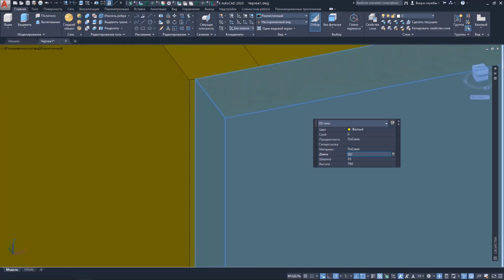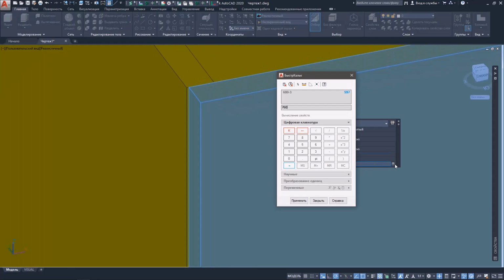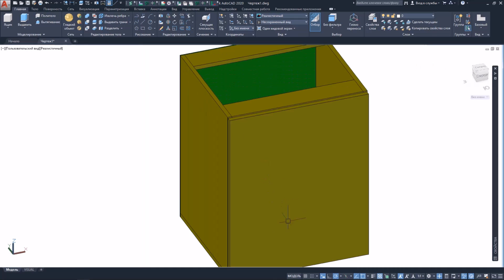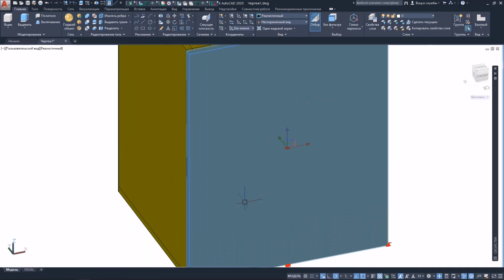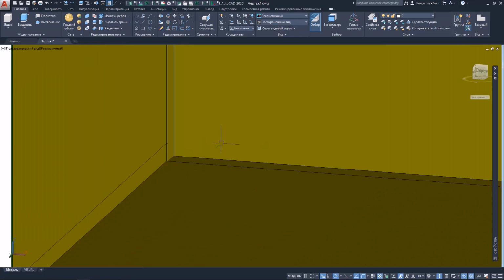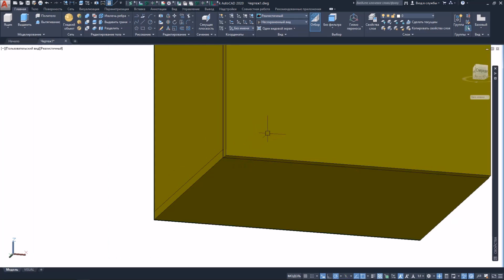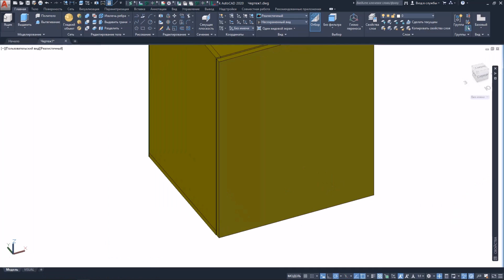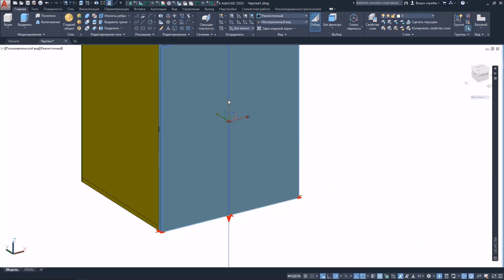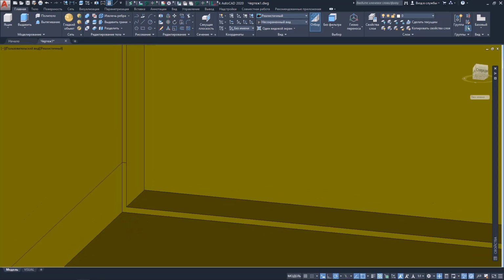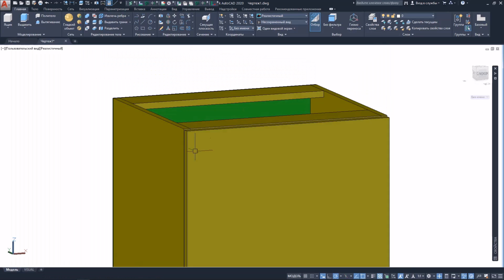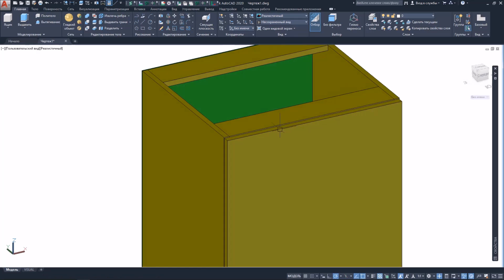When you make your solid shorter using height, you should notice that we have a base at the bottom. So you should move your detail by half of the dimension that you gave to have similar gaps. Let's move it up by 2 millimeters. So we have gaps of 2 millimeters at the bottom and 3 at the top.